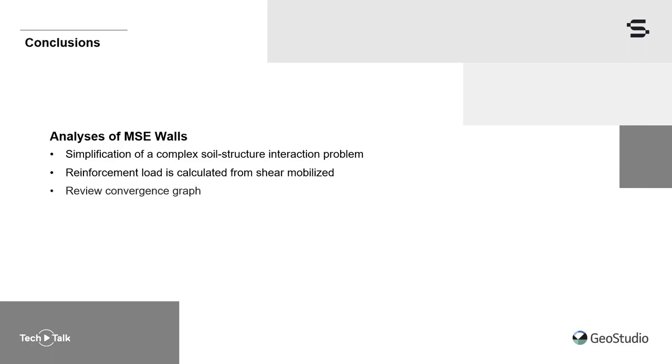It is critical in all slope stability analysis, and especially when reinforcements are involved, to review the factor of safety versus lambda convergence plot because point loads lead to high base normal stresses which manifest in high strength contrasts between adjacent slices. This is the fundamental cause of convergence problems in a limit equilibrium analysis.